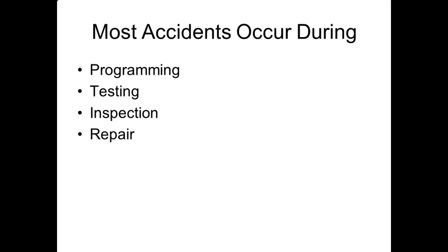So what they do, this is OSHA and this is RIA, all these robots do this: when you jog the robot, the speed is limited to 250 millimeters per second, or about 9.5 inches per second. And it's been proven that if the robot hits you, you have time to get out of the way of it.